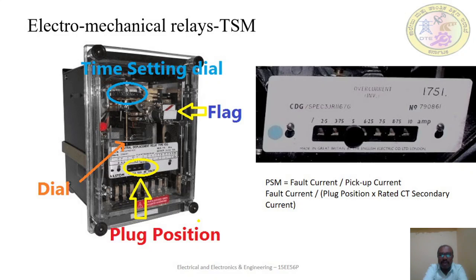We know that a fuse performs both detection and interruption functions automatically, but its use is limited for the protection of low voltage circuits only. For high voltage circuits, relays and circuit breakers are employed to serve the desired function of automatic protective gear. The relay detects the fault and supplies the information to the circuit breaker, which performs the function of circuit interruption. Next, what is meant by protective relay?